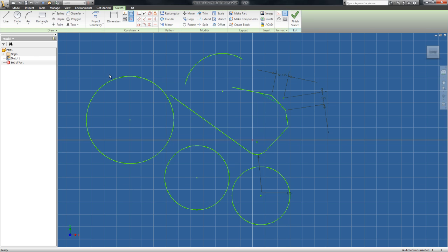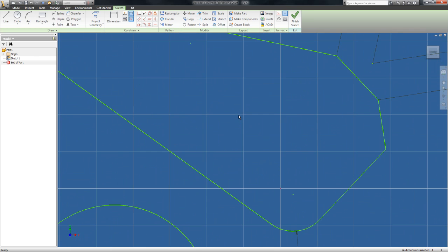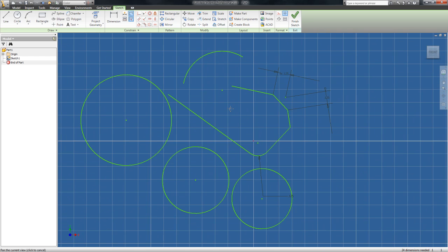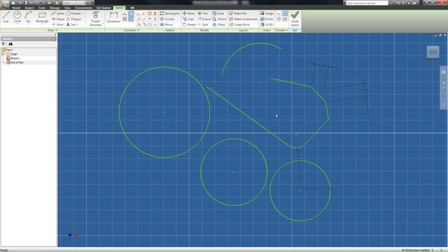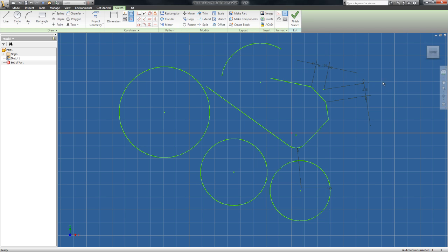Okay, getting up to the time limit now, so we'll just keep it short. Basic mouse and view stuff. If we scroll the mouse wheel, we'll zoom in and out. Also, if you click and drag the mouse wheel, that'll pan. You also have view options over here, such as pan and zoom. And once again, there's shortcuts on the keyboard for all this stuff. If we want to draw a line, we hit L, and that'll be a shortcut for the same thing as clicking the line button.